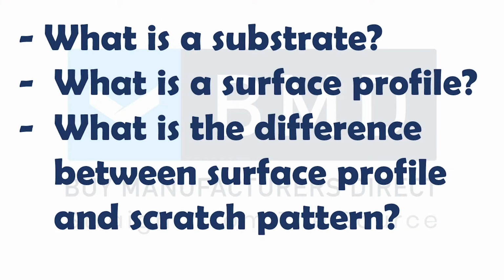Okay, and in a lot of the online trainings that I've looked at, they use the phrase scratch pattern. How is scratch pattern compared to surface profile? Is it the same? Is it different? Is it just semantics? It's hard to say. It depends on the context when somebody says scratch pattern. Normally, scratch pattern is a conversation had with regard to polishing, because the scratch pattern needs to be removed and refined. In the case of a coating, the coating doesn't really know how to discriminate between one scratch and another.